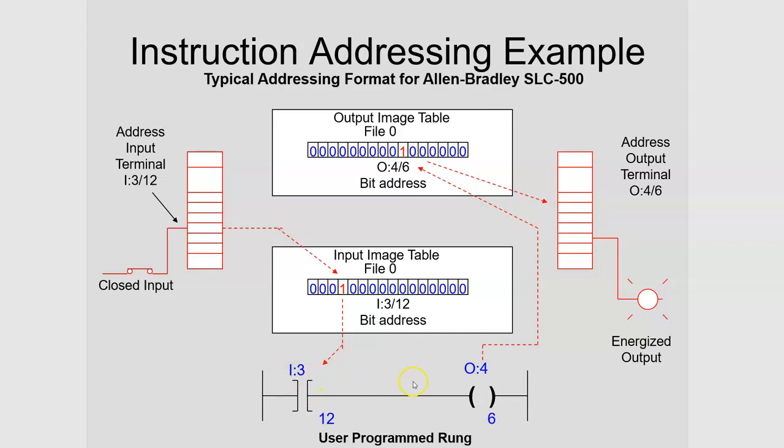Now here's a program you wrote, and you mapped it to this bit position, I3. And you use this command, and since you use this command, if it sees a 1 there, then this is going to be true. Now you only have one instruction there, so it's not AND logic. If I had another one of these, it would be AND logic. We don't have a logic command, other than the inverter that has a single input. It's got to be at least 2.